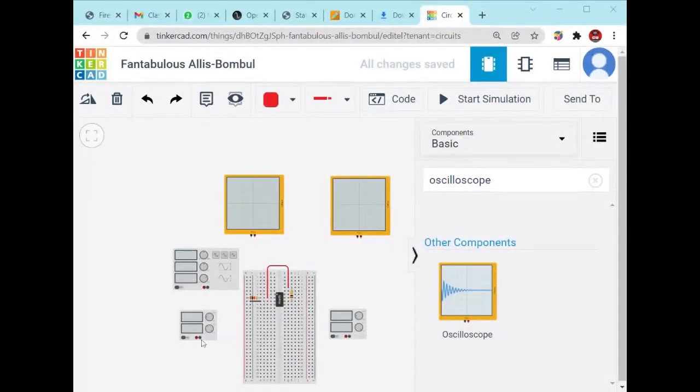From here you will find this negative pin. Select this negative pin and connect it to the last pin. This is your negative pin. I'm making this negative black. Now this one is your positive. The positive should be connected to this.